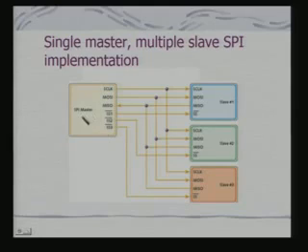Here actually the master needs to incorporate a similar kind of a decoder. Okay. So, master would know the address of the slaves, and it would provide in the software the address to the decoder, and decoder would generate the appropriate slave select signal which would flow into the slave, so that they are selected and they are able to respond to whatever is coming from the master.